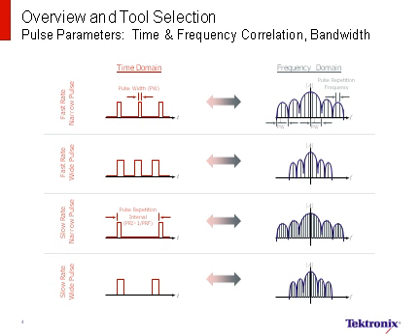For the example shown here, the frequency domain information can be translated back to the time domain: the pulse width is 1 over the side lobe span, and the line spectra come from the pulse repetition interval, 1 over the PRI line spacing. To have correlated measurements of time and frequency, one must have an acquisition system with a sample rate and bandwidth and a memory depth able to collect the entire signal of interest. This includes the envelope rise time, correlated impulse spectrum, and the pulse train for a defined number of pulses.